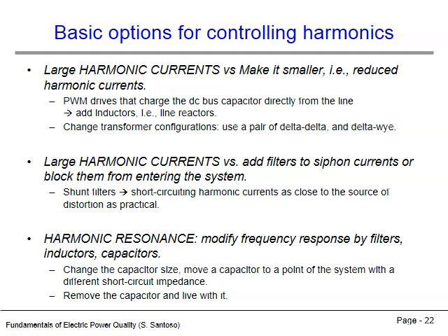The load itself can be altered, changing its operation or the manner in which it connects to the grid in order to reduce the harmonic currents that it produces. Additionally, loads can be connected in parallel to a filter, tuned to series resonance with the harmonic frequency in question. This creates a short circuit for currents at that frequency, keeping them from entering the larger power system.